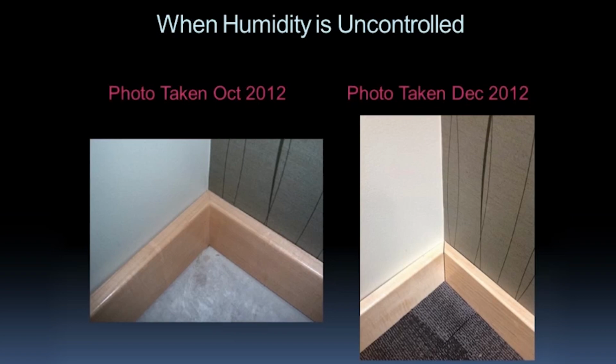These panels actually were over the entrance door that all of the subs were using to bring in materials and going in and out. So the door was opening and closing constantly. And ultimately, the panel was right above the door and moved so much that it had failure of the edge banding. One thing I will point out: because they were maintaining the data loggers and they reviewed the information with the GC and the architect and the building owner, they actually required that the HVAC unit for the building be redesigned to be able to maintain the required humidity levels.